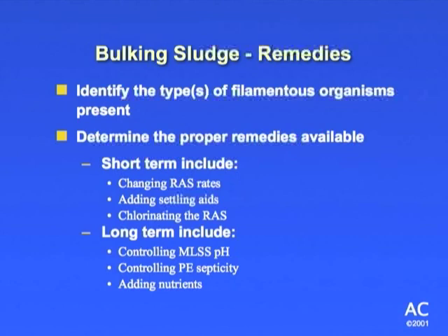Again, if you have a plant that's for the most part getting domestic wastewater coming in from a wide, varied community, it's pretty homogeneous and pretty well balanced out, a good diet for the plant. It's oftentimes when a plant is swung by high infiltration or industrial flow that it will throw the plant. Or for a smaller plant, if you're taking a lot of septage, it can start throwing the plant as well.